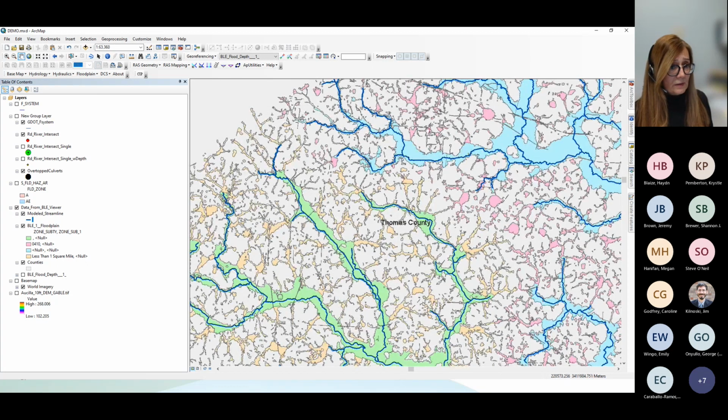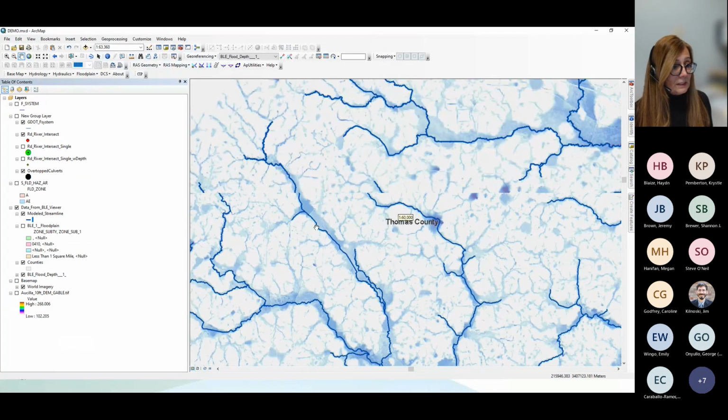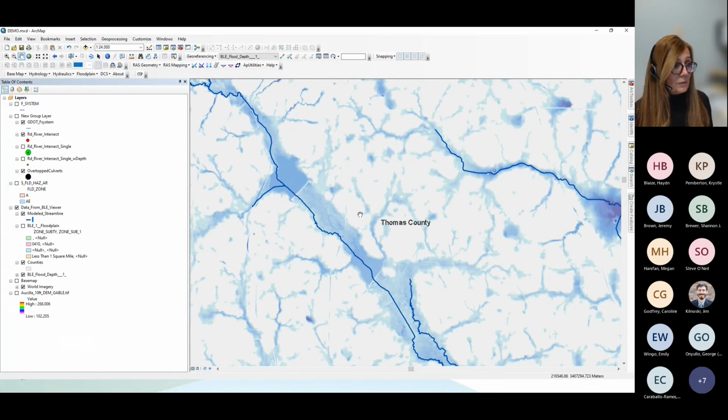And again, as you can see, the floodplain mapping is shown in different colors depending on the drainage area to each location and also the average depth of flooding. We have 4 categories of floodplain here. We also have the county boundaries, and lastly, I have downloaded the 1% depth grid. So you can see if you zoom in, this data set is providing you information about the depth of water in the floodplain. So this is the first set of data that we're going to use for this analysis.